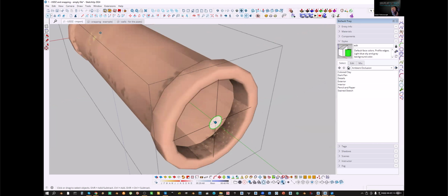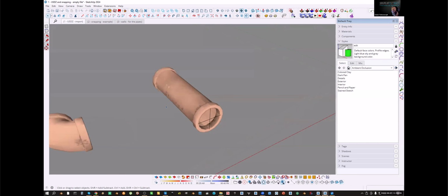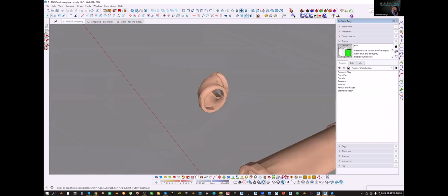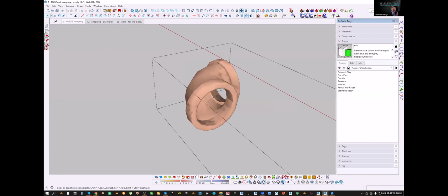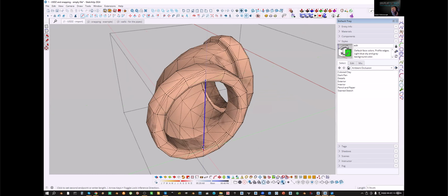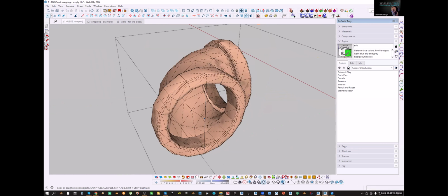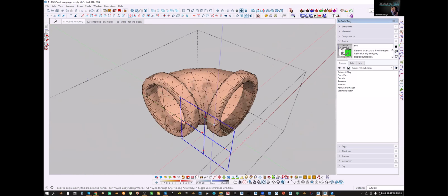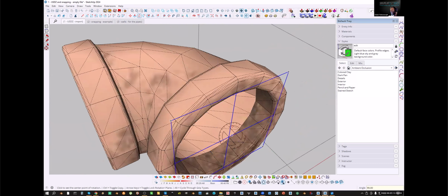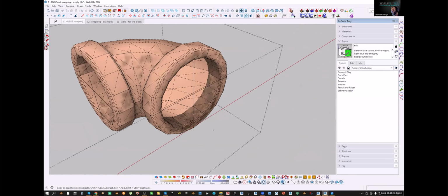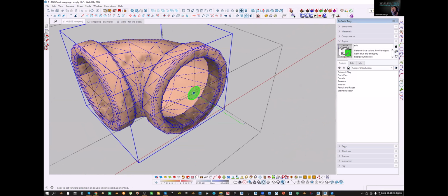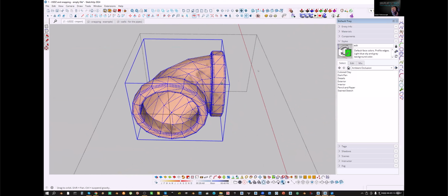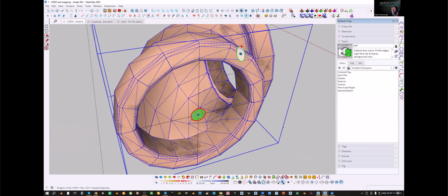So in this case, we can click that, reverse snap, and in this case, it is gonna work properly. So let me just prepare one more object. I'm gonna draw those additional lines, which will be very helpful here. Okay, 90. I'm gonna make a copy from this one, move it around and rotate it, 90, enter. All right, and now I'm gonna add the snap, add snap, arrow left. Okay, and one more, add snap, arrow right.